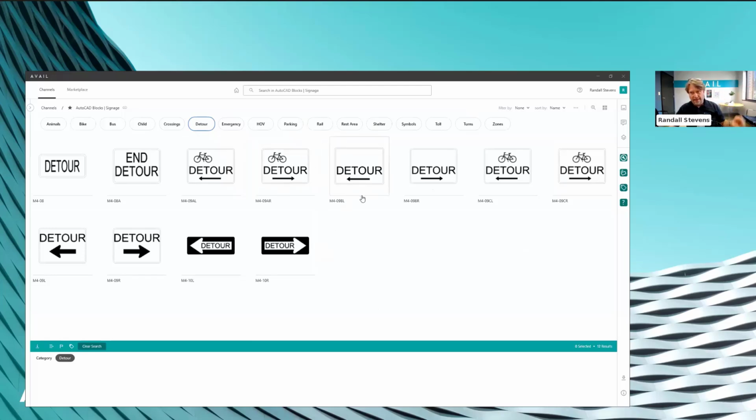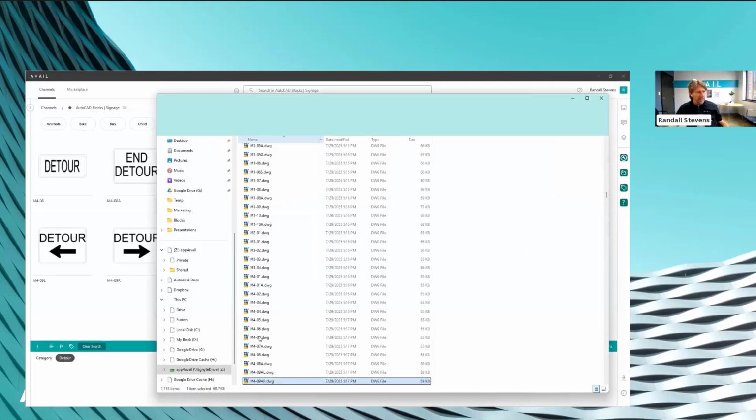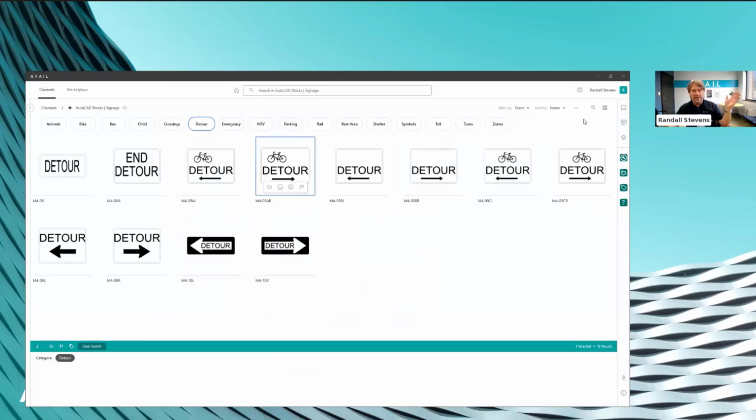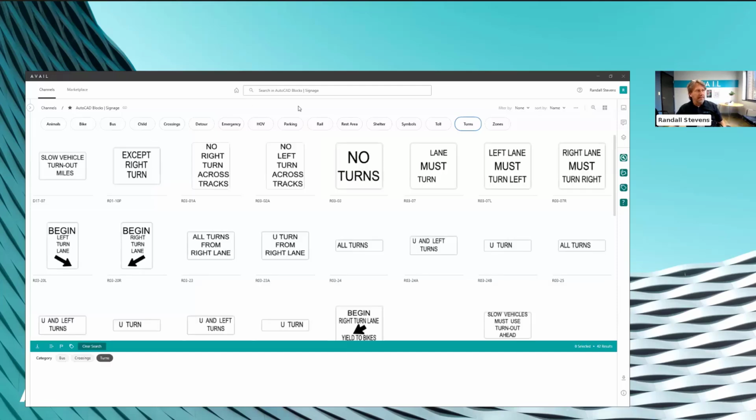And then you can literally just drag this over. This is just a DWG file. If I right click and say open the location, you're going to see over on the network, there's a little DWG that was harvested out of that container library, little 69 kilobyte DWG file with that piece of information in it. So it allows me to just drag and drop this over into the interface. I'm going to show you we've put browsers back in the AutoCAD and Civil 3D interface and I'll just hint, we have a future for that back into the Revit workflow that we're thinking through right now. But anyway, this is the value.